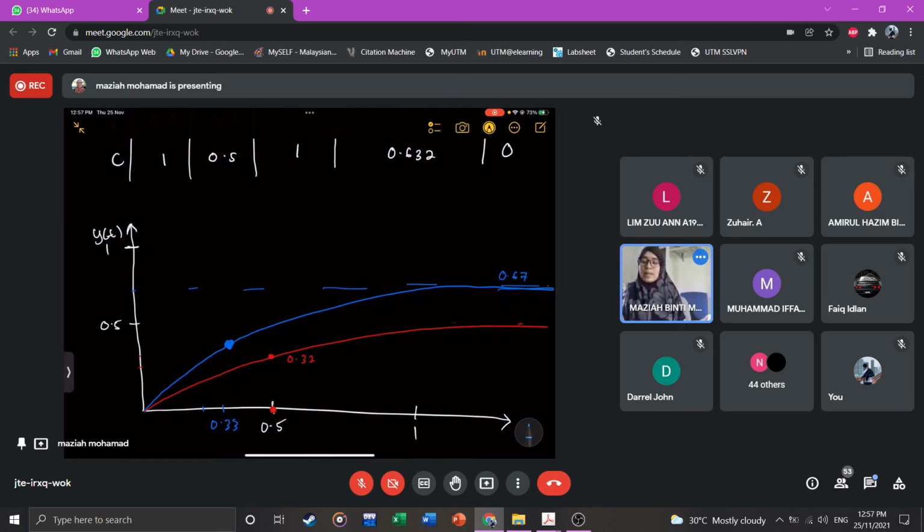And in terms of steady state error, without any controller the steady state error is 0.5, and it reduced to 0.33 after you change the gain to 2. So by adding a P controller, you are able to improve the response of the system, and second, you are able to reduce the steady state error.